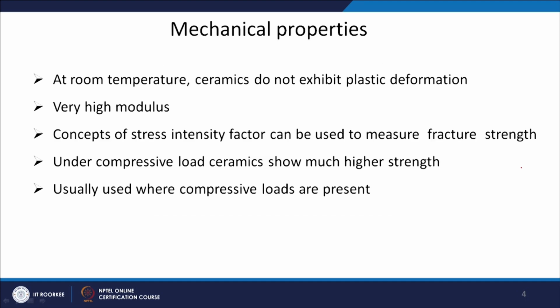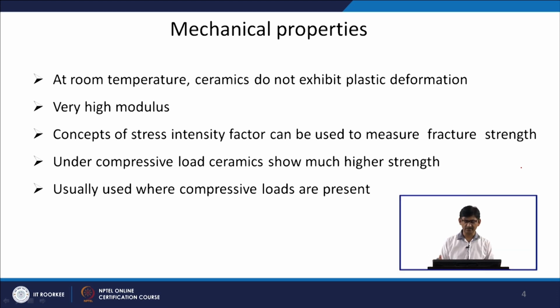Regarding mechanical properties, at room temperature ceramics do not exhibit plastic deformation. They only show the elastic deformation part and then fracture. The main thing is the nature of the bonding, because they have covalent or ionic bonds. A dislocation cannot be introduced here, because that will bring an additional ion at the end, and we will not be able to maintain the charge neutrality there.